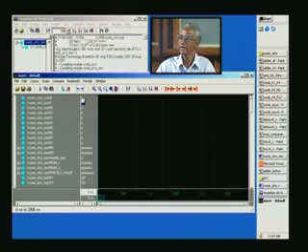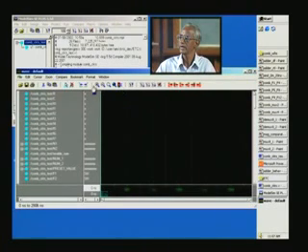So in this column right now it says XX because the simulator has not been run. In order to run, we'll just see what commands are there. And we have some lens here, for zooming in. If you press this one, you can zoom in. And before that, let us get the waveform. Then we can do all this. So if you see here, restart: if you want to restart the simulation. But straight away we will go for run all.